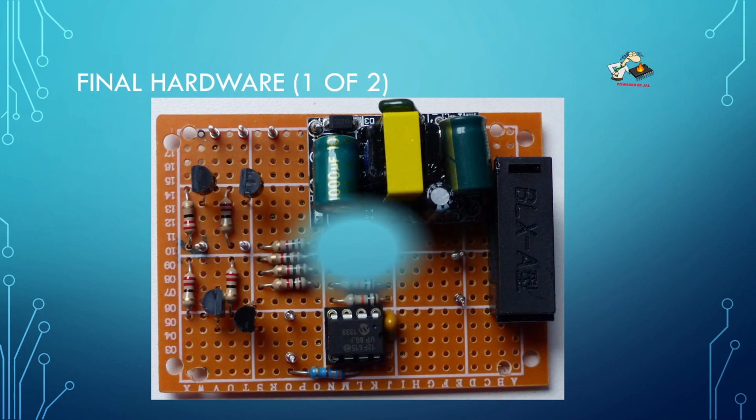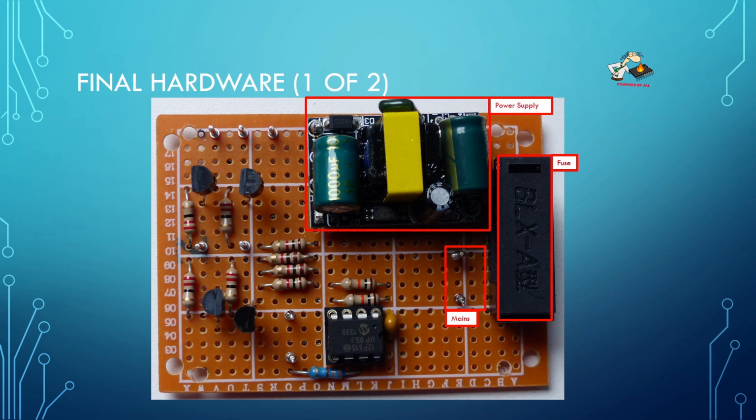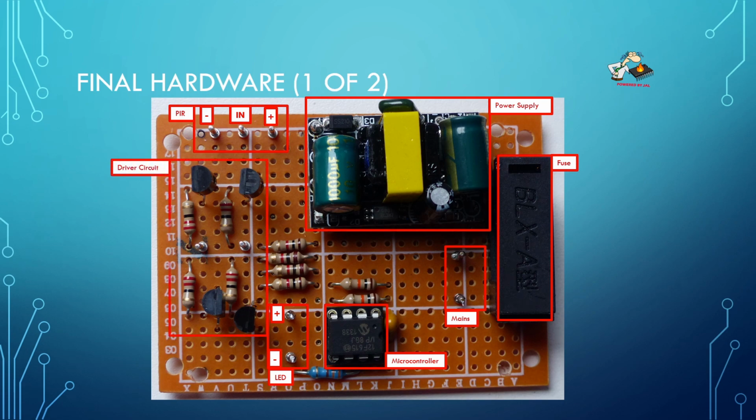So the hardware was built on a breadboard. It starts with the mains connection, then I'm using a fuse for safety, which is then connected to the power supply. I'm using here the PIC microcontroller. I have the connection for the passive infrared receiver, also the connection for the LED, which I did not mention in the schematic diagram, but it's there, and the driver circuit where you can connect the buzzers to.